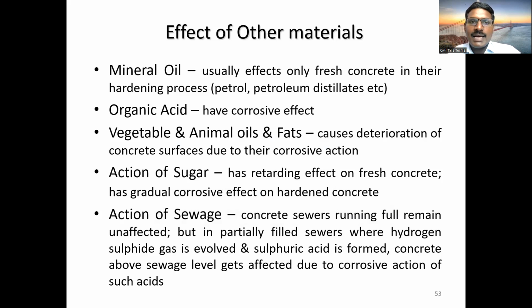Then organic acids, due to which corrosion will occur. Then vegetable and animal oils and fats cause deterioration of the concrete surfaces due to their corrosive actions. Then action of the sugar: sugar has a retarding effect on the fresh concrete and has